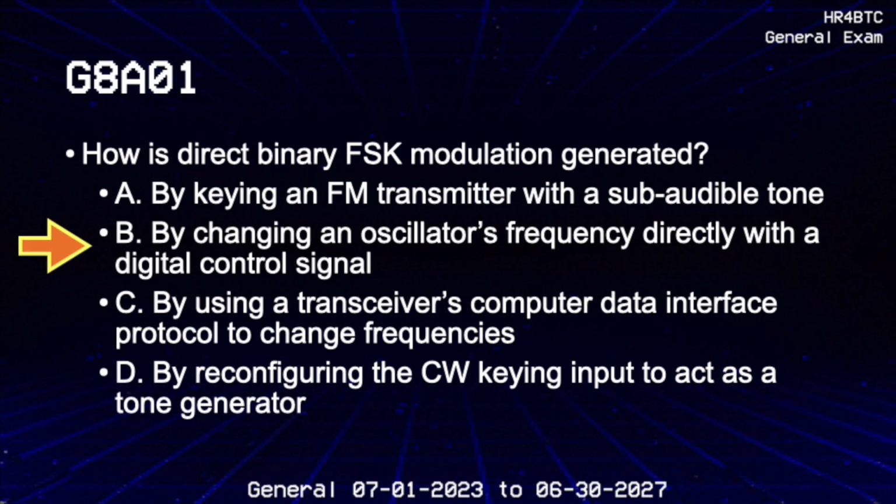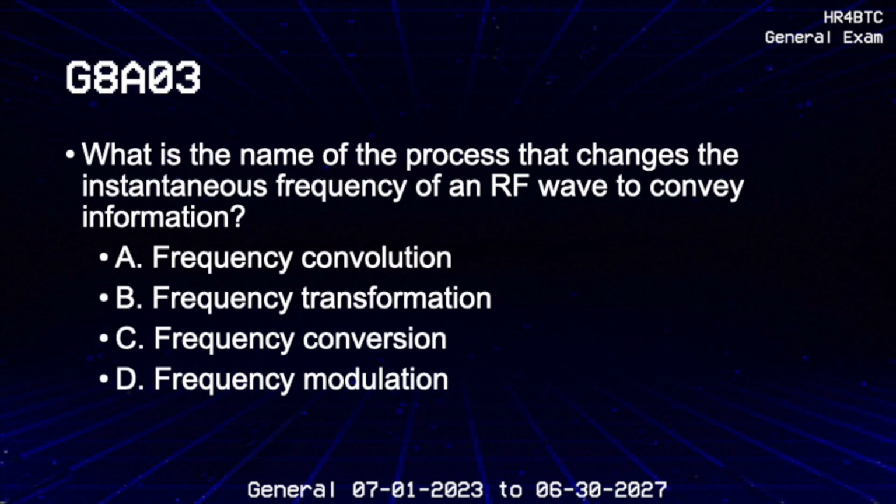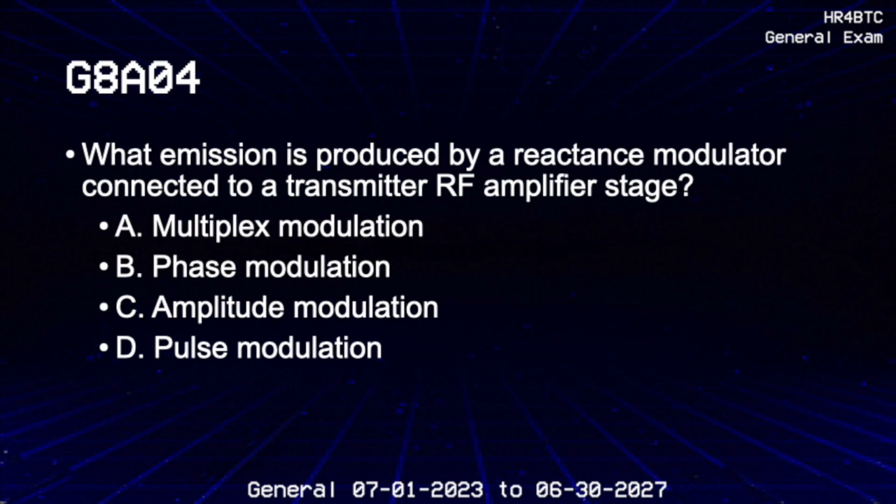By changing an oscillator's frequency directly with a digital control signal. What is the name of the process that changes the phase angle of an RF signal to convey information? Phase modulation. What is the name of the process that changes the instantaneous frequency of an RF wave to convey information? Frequency modulation.